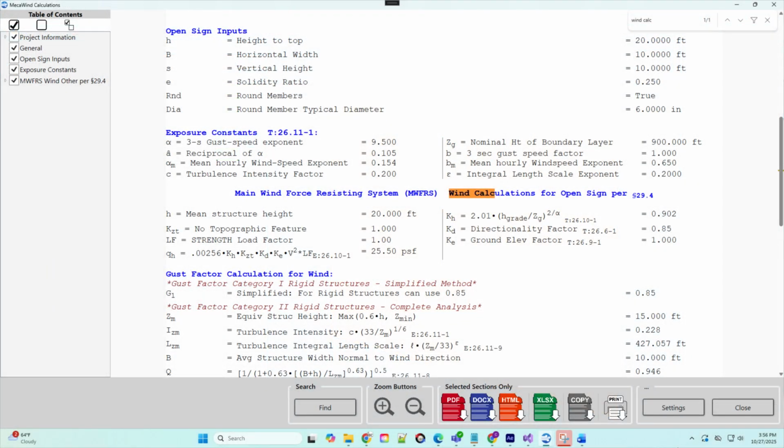The open sign could be used for other structures that are not necessarily signs but might be rectangular and more than 30% openings. For example, let's say you have a structural frame that is supporting equipment, piping, platforms, etc. When you look at it, you estimate that it is less than 70% solid. Then you might use the open sign to calculate the total wind load on the structure and the objects it supports combined. With a little imagination, you can find that there may be many non-sign structures where the open sign criteria might be useful.